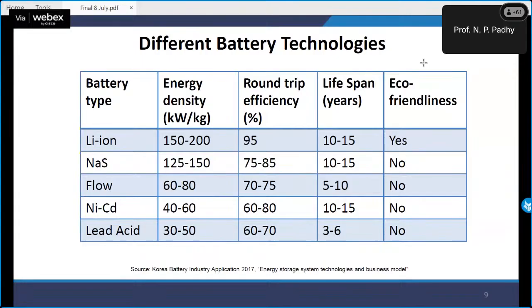So whatever I've generated, if I like to take this water back to the dam, probably I'm under loss. So no one will do it. Even today, in pumped hydro storage systems, for 1 cubic volume of water, if I like to discharge, I spend 1 unit of energy. When I take it back, I have to spend more than 1 unit of energy, considering the efficiency.